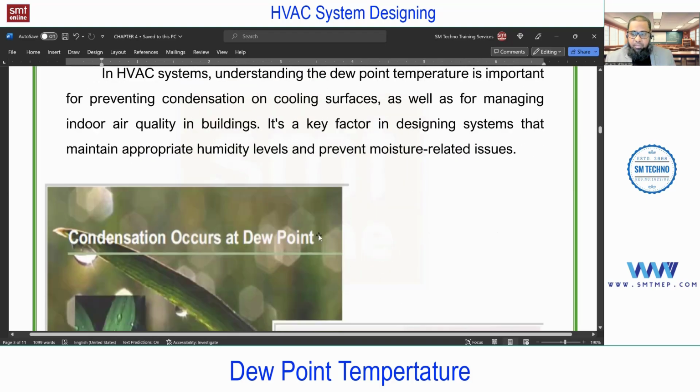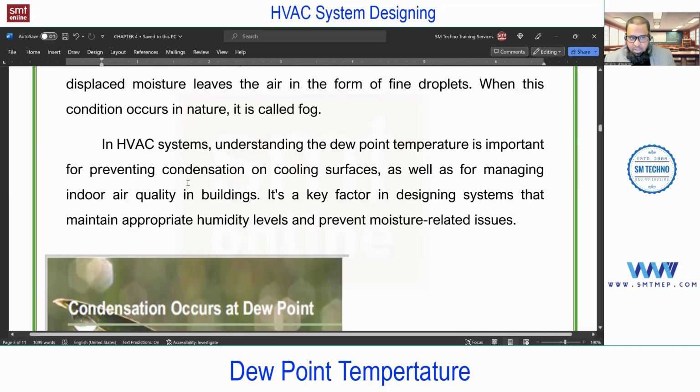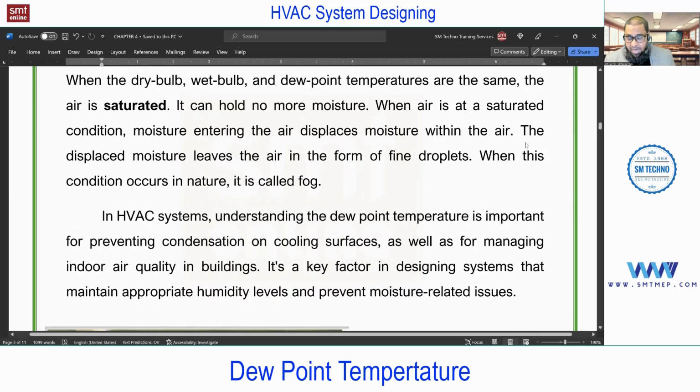So next, how is the humidification process completed? I mean, we need to sprinkle the water. Humidification. Okay, you see, what we discussed just now is dehumidification. Humidification means adding the moisture, adding the moisture with the heating. So we may add the steam in the duct,